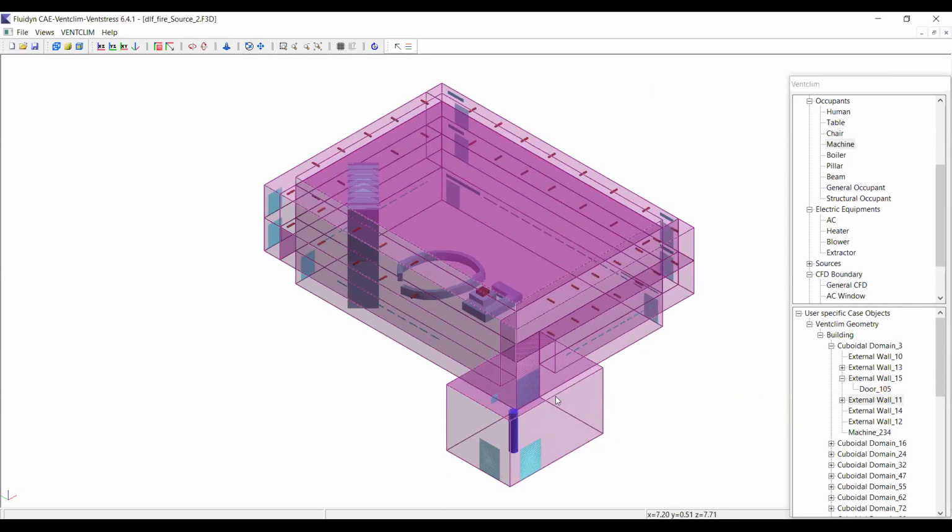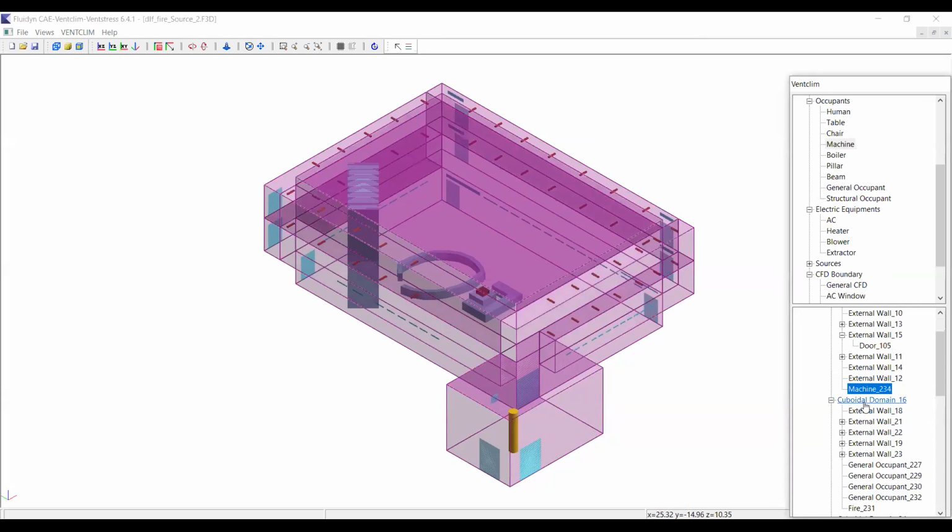I was also talking about some subgrid models. If you activate subgrid models, the flow will generate some source terms, and we are able to capture, suppose I have some flow along this, even the turbulence behaviors, everything on a coarse mesh. Apart from that, these are the structures we have. Similarly, we have different domains.